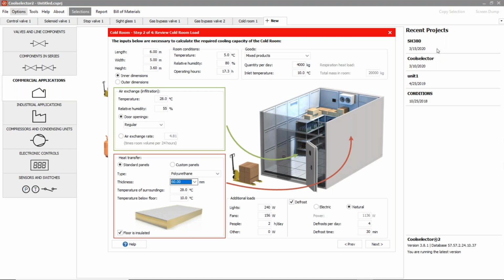Any more questions? Yes, we have a few more. The question is: for selecting liquid line accessories like expansion valve and solenoid, is the liquid line size not required? I recommend you select the expansion valve first based on the conditions: capacities, pressure drops, and the types, and always last, the size.